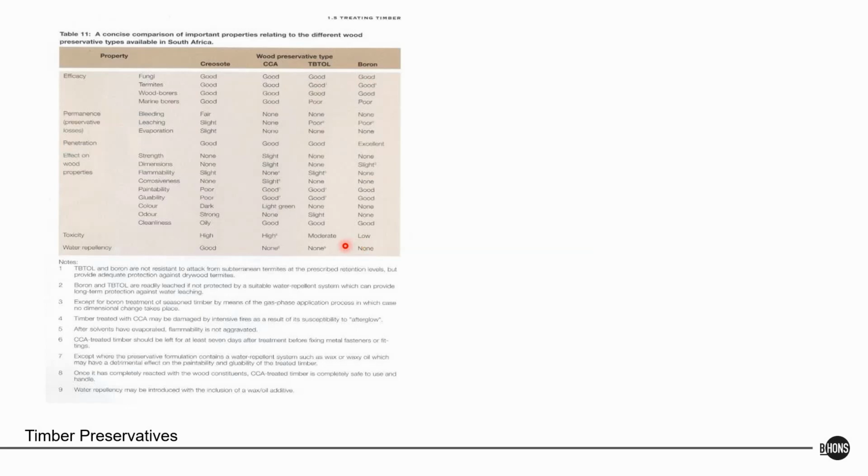Then the last thing is, when you use gum poles, remember that gum pole structures typically start to delaminate, or they turn and twist as they dry out, and you'll see them splaying a bit. You start seeing the timber like little fingers sticking out from the edges, and that's actually the problem of gum pole structures, or specifically Saligna gum poles. So it's best to use end plates. It's a nailed plate that you put at the end of a timber piece, or you take a piece of wire and you bind the edges, and then you know that they will last. And then they last very long.